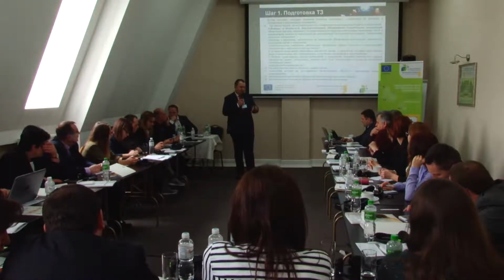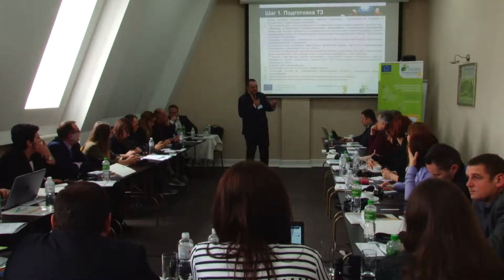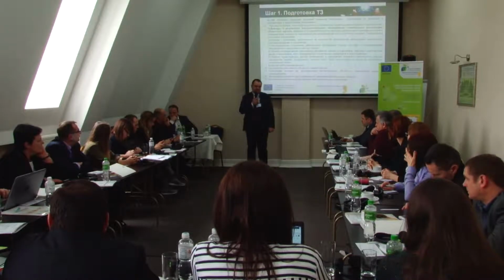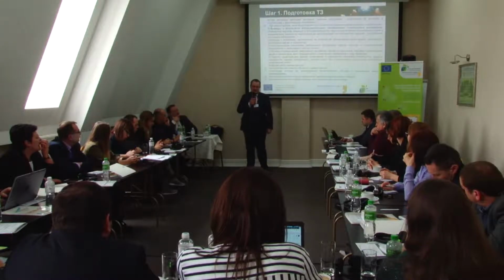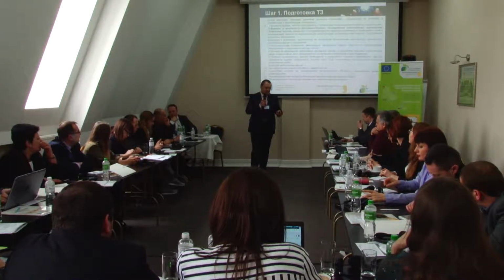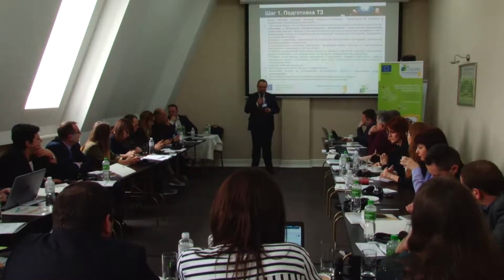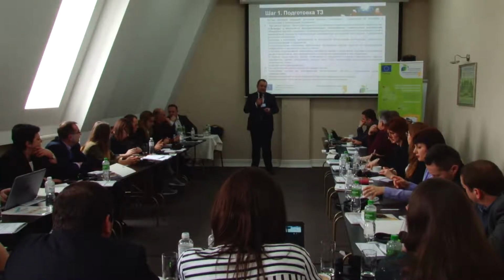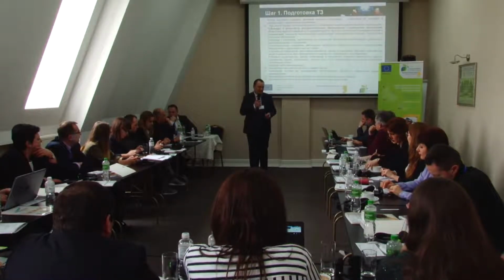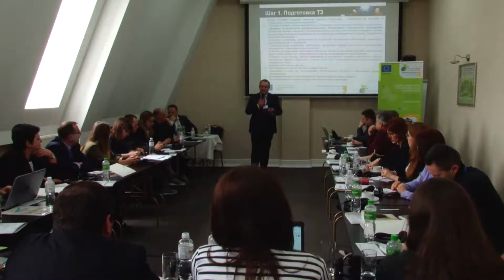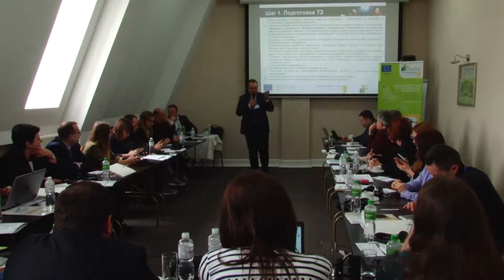Mainly that is for buildings, and you as the customer, within the technical assignment, within the terms of reference, should provide the designer with the conclusions from the reports saying that your building is suitable for thermal refurbishment and it has no deficiencies as of the current date, and the carrying capacity of this building is sufficient to bear additional load related to the additional insulation weight or some other, heavier roof.